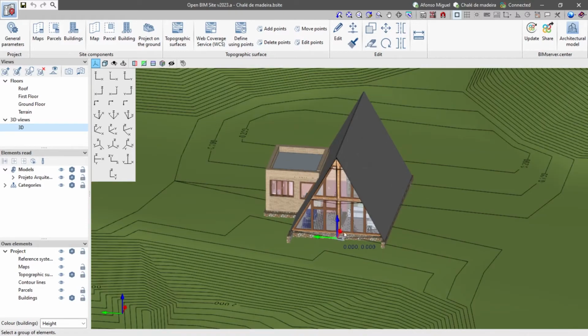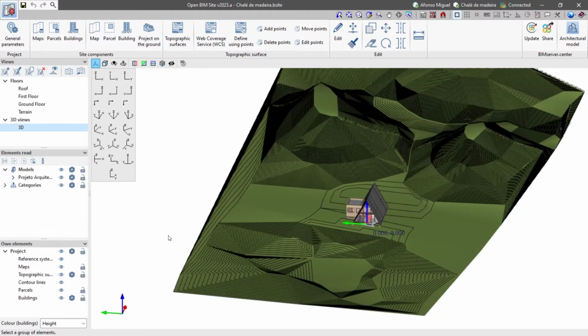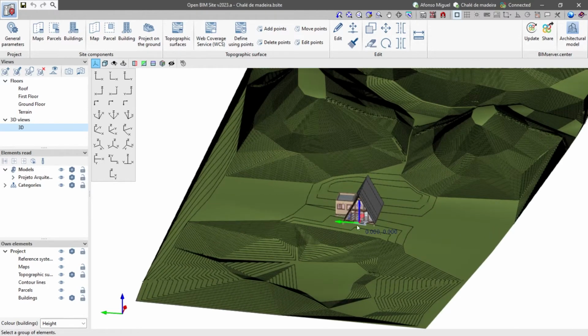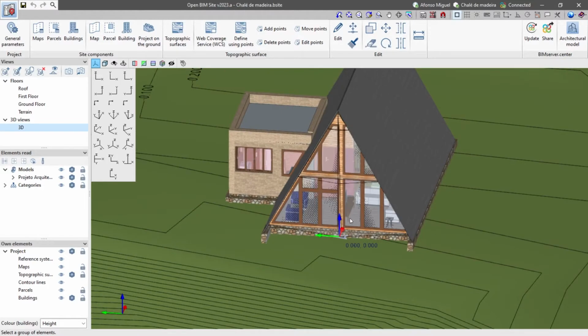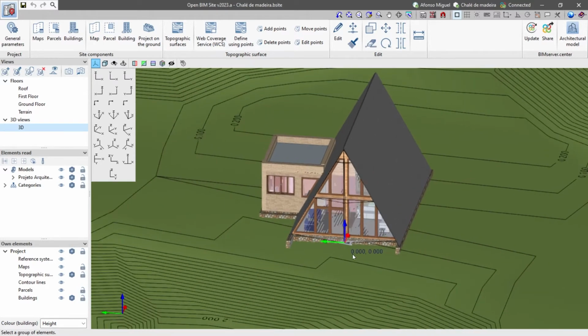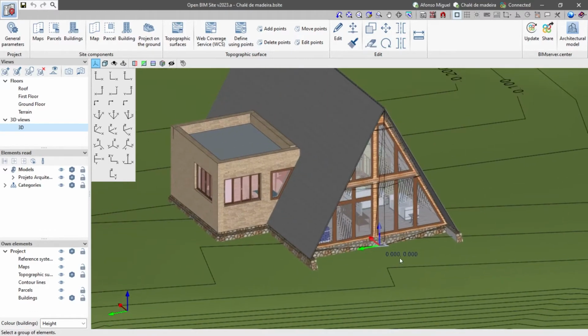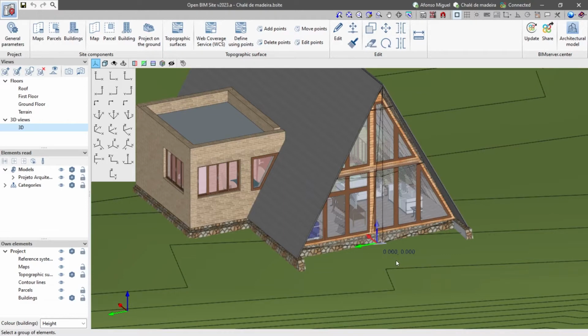Okay, because maybe you have the origin far. Let's suppose the origin is somewhere here, and when you need to orbit or find or zoom when you are in Twinmotion, if the origin is too far, it's going to be a little bit more difficult. So my recommendation is that you always work with the origin near your building. Although this is a normal situation in almost all projects, we place the building near the geolocalization point, or a 000 point that is our reference. So I just recommend you check this aspect before you start exporting to a render tool.